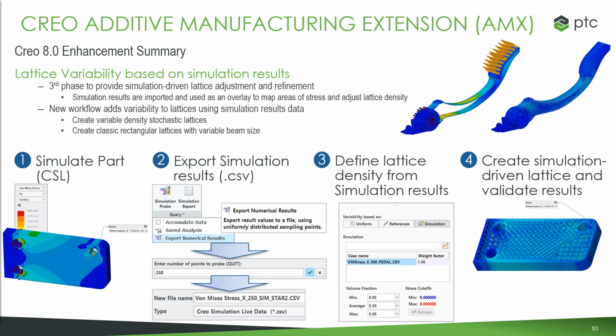So the idea is the ability to build your printed lattice, 2.5D or 3D, inside your CAD model, with the idea that you want to validate that inside CAD. If you're going to 3D print production parts, you're going to put a lattice inside those parts, and you want to make sure that they meet the structural requirements. So the lattice feature was introduced there. We could build that. There have been enhancements along the various versions of Creo. We introduced stochastic lattices, formula-driven lattices, and the like through later Creo versions.